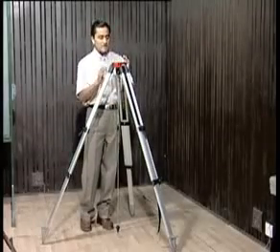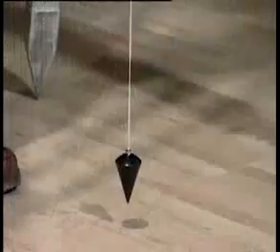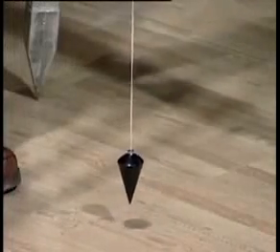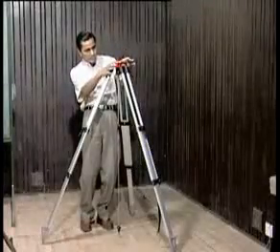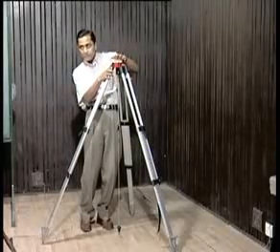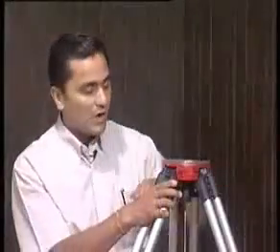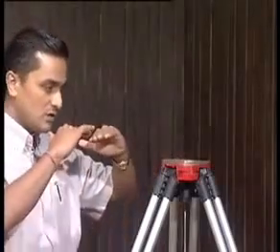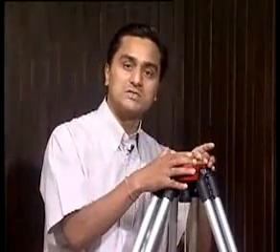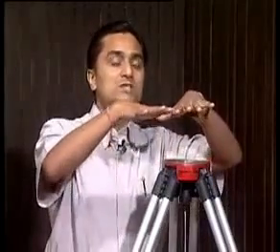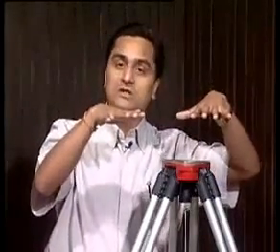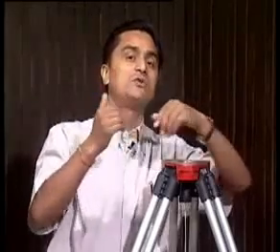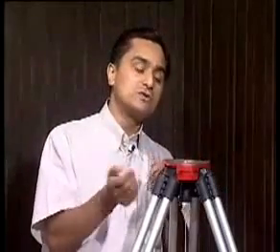Now to do the exact leveling and centering, I observe the head of the tripod. That's the tripod head. I want to ensure that this tripod head is level, because this is required. I will put my instrument on top of this. I will need to make my instrument horizontal. The horizontal plate of the instrument should be horizontal. So before I do it in the instrument, I should ensure that my tripod head is horizontal. So how do we ensure it?